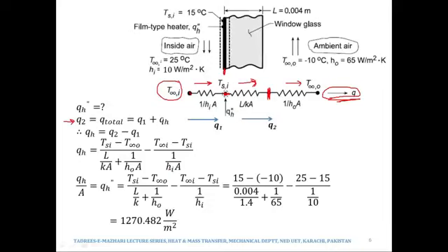What we do not know is the area. So we would be working in terms of per unit area. We will take area from here into the numerator, and then we will take the area common from both these terms, and then we will bring the area into the denominator of QH by A, and we would be calling it QH double dash, meaning heat flux, thermal heat flux, heating flux.